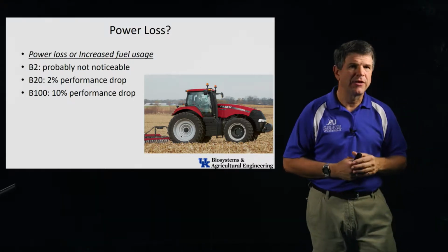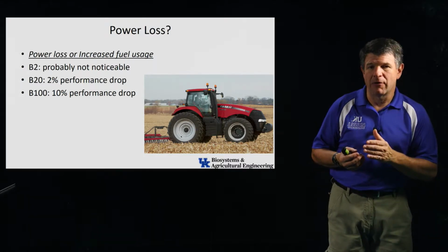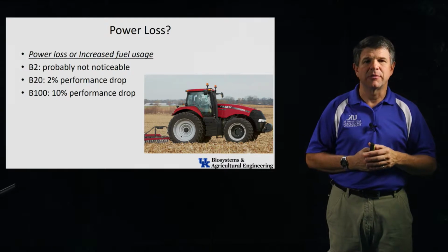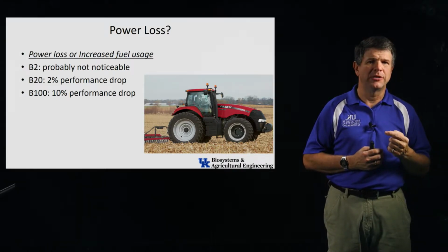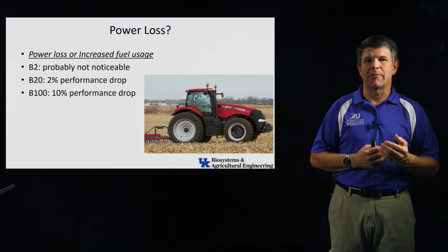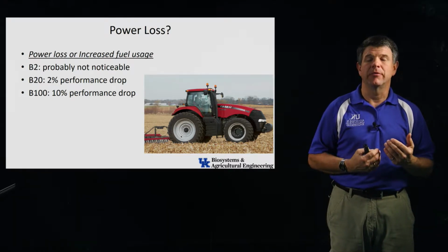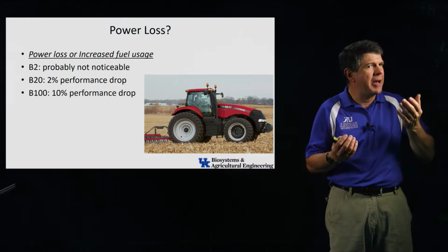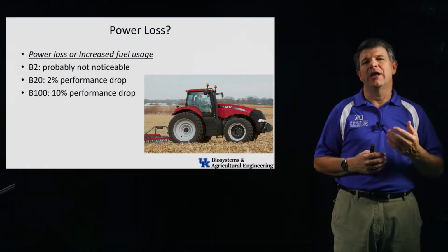Again, this could manifest itself in two different ways when I change fuels. That biofuel has a lower energy density, so it doesn't have as much energy in it. So how will the engine respond to that? Will it actually use more fuel to do the same amount of work, or will it put the same amount of fuel through and just not be able to do as much work and not have as much power? And you'll see maybe combinations of those different responses, depending on how the engines are controlled.